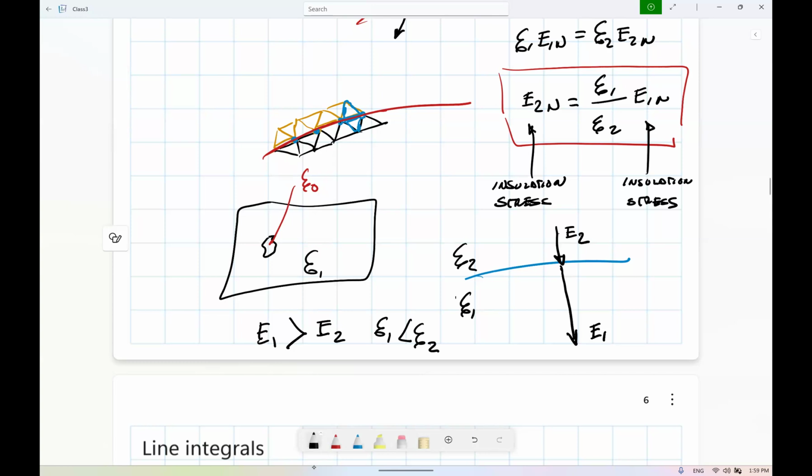Particularly the transformer is one that will give you trouble if you don't use materials that have similar permittivity. Okay, so we know that we need paper or we need several layers of insulation. Typically on a large transformer, we will have paper and oil. And we try to make these two systems as close as possible in the insulation to prevent this sort of amplification of the electric field.